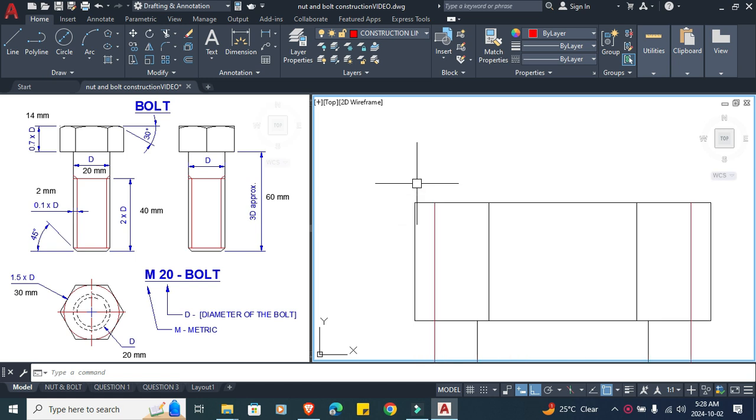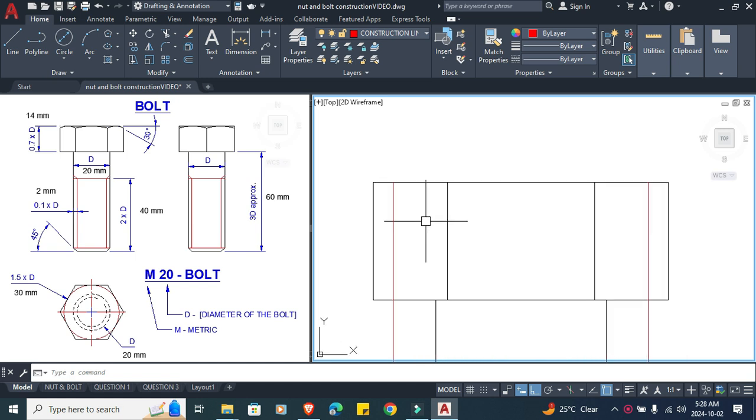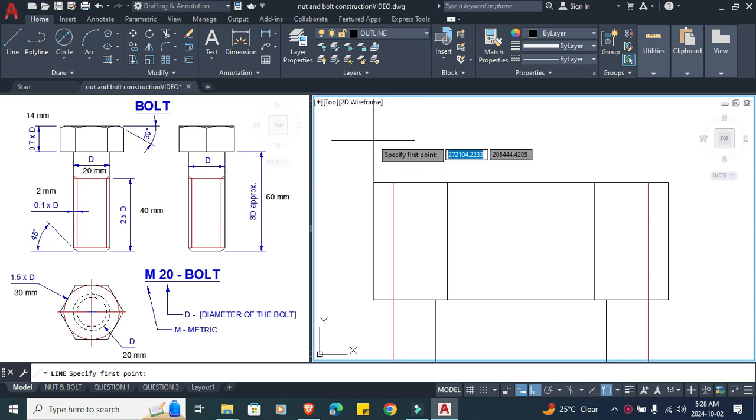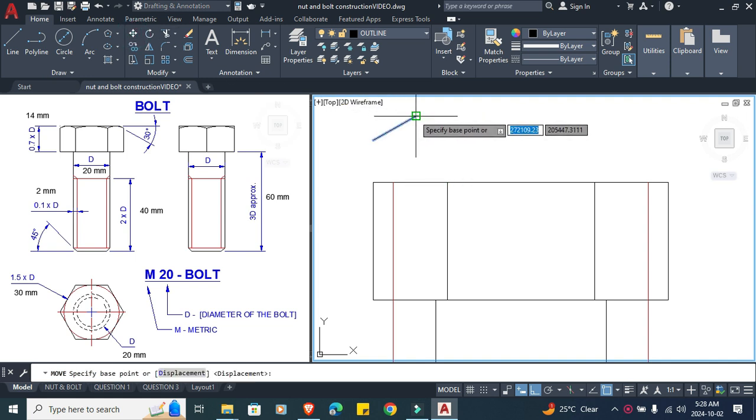Now we are working in this area here. So to get the curves here, we need to chamfer here the 30 degrees. So in your outline layer, draw a short line, about this much. Take this line and rotate it 30 degrees, and then move this line. Select it, press move, holding it at this end, and drop it here.